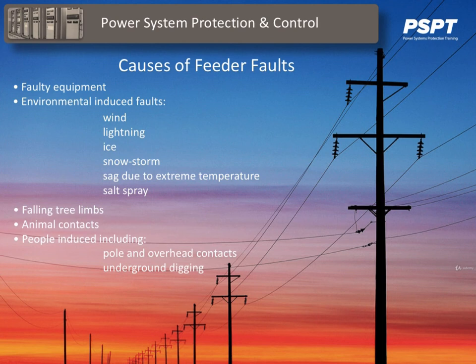A key advantage of microprocessor-based feeder relays is the ability to protect against these unusual faults while improving the operation of the distribution system through flexibility, programmability, and communications.